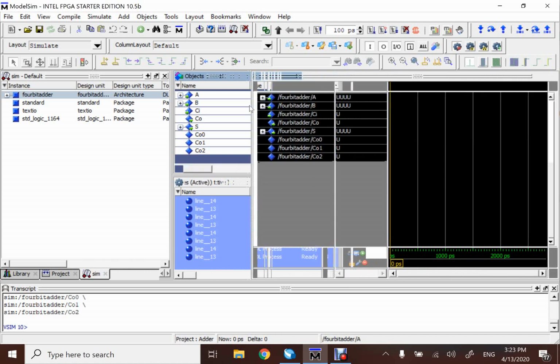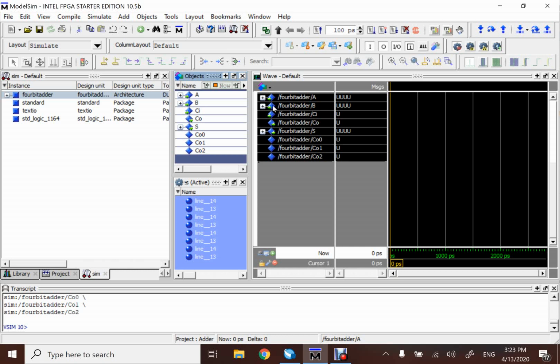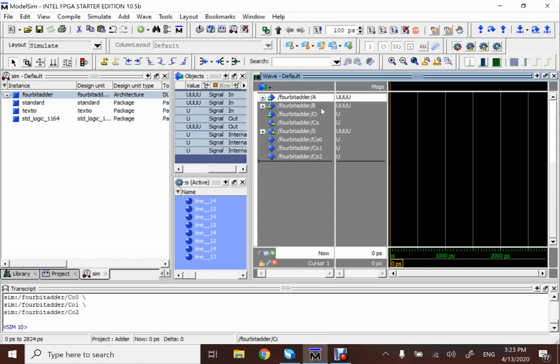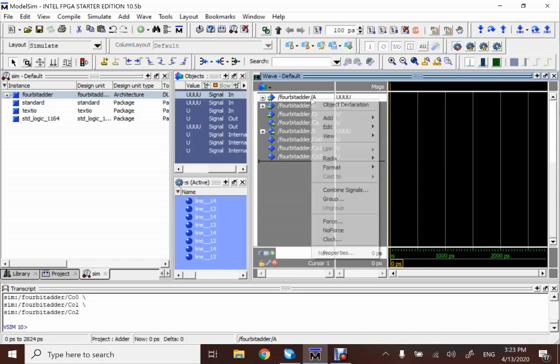So far we've only used clock to assign values for the input, but in this lab, for this particular circuit, we're gonna introduce something named force. We'll use it to assign a specific value for a signal. We can test by adding, this is an adder, right? And it's a 4-bit adder.